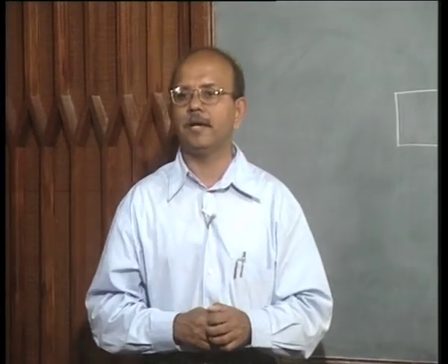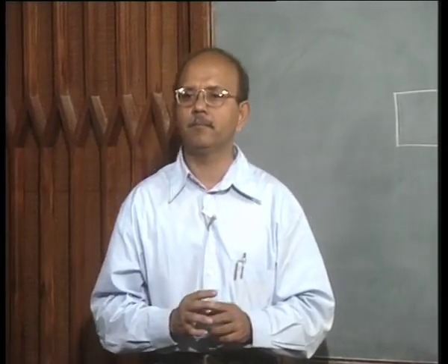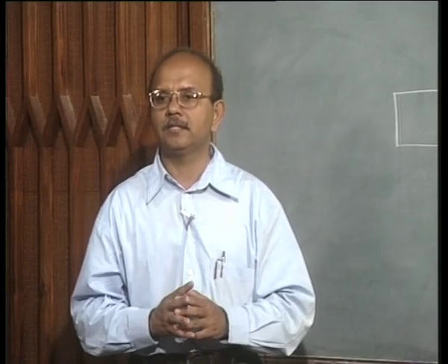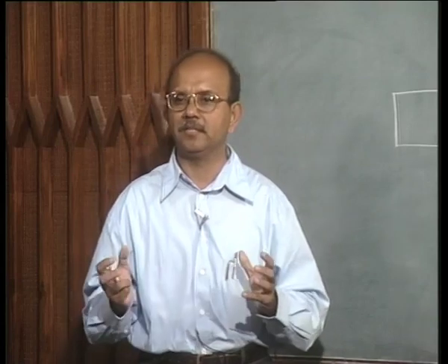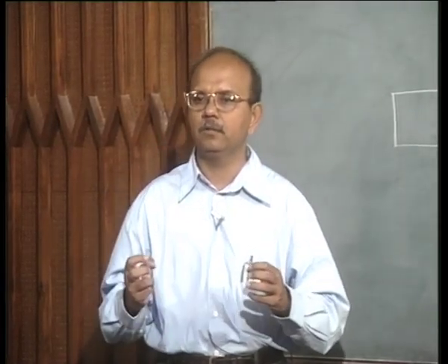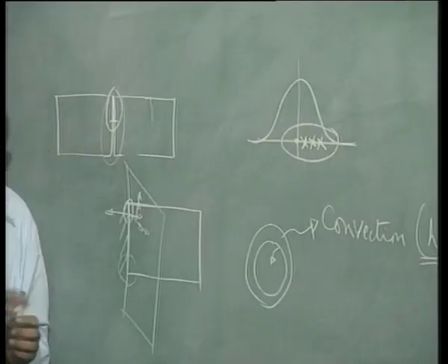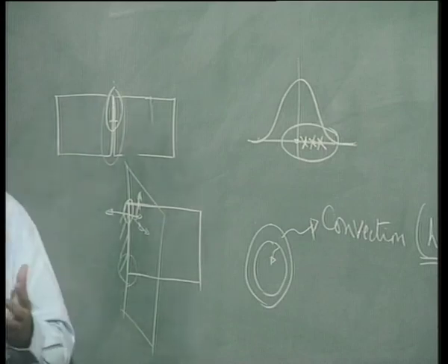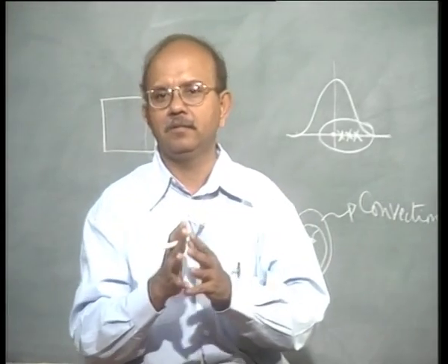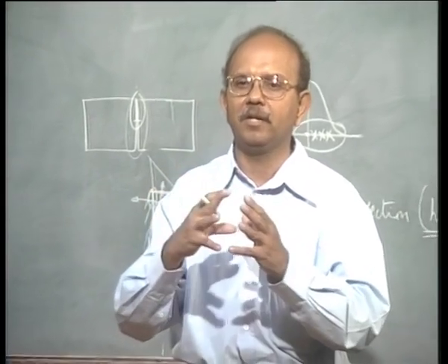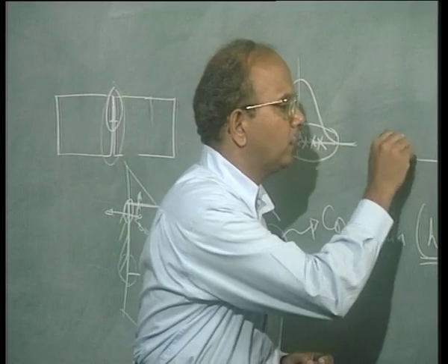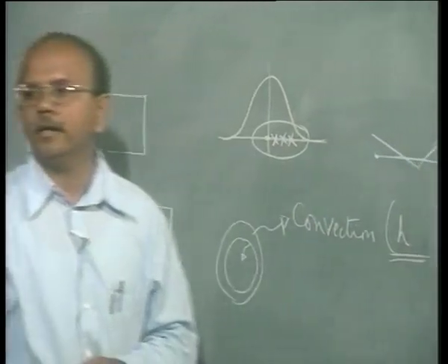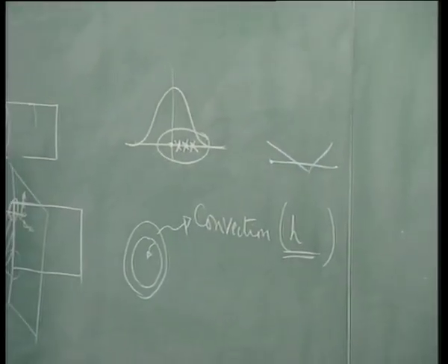The problem is that contact elements are such that when there is a tensile load, say when the gap increases, the contact element won't act. It only stops penetration, which I call delta. For example, there are two nodes and one node trying to penetrate, and that penetration is what is stopped.